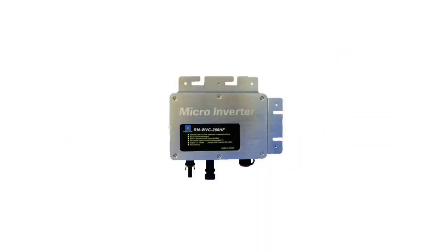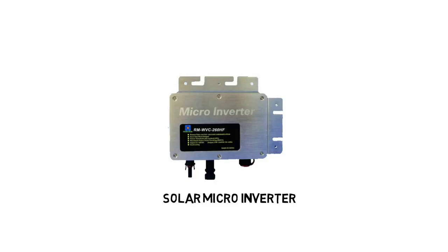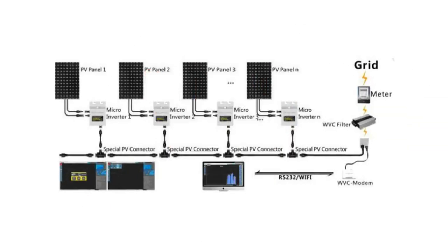If a system with AC output has to be designed, then there is an advantage if microinverters are used. Solar microinverters are small inverters that are connected to each individual panel as opposed to large inverters that deal with the output of all the panels. The advantage is that if a single panel becomes shaded, then the output of the whole string of panels isn't affected. This is because each microinverter feeds into the grid independently. This would not be the case if one central inverter was being used.